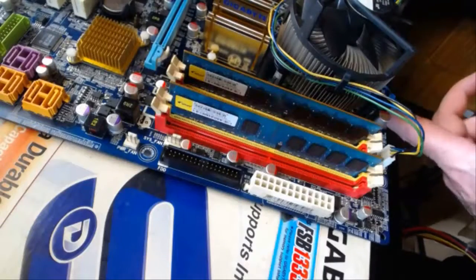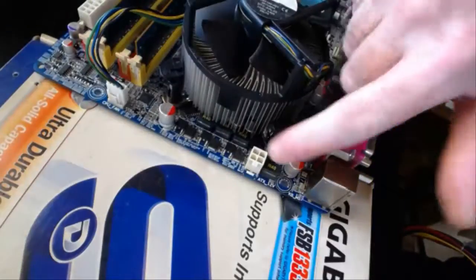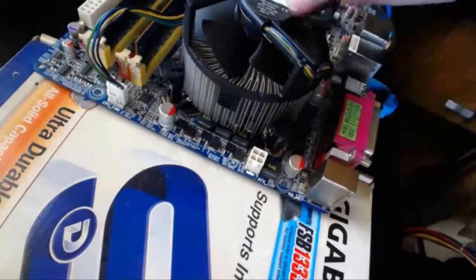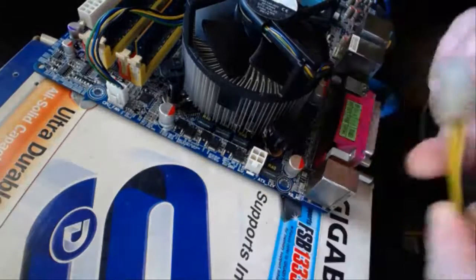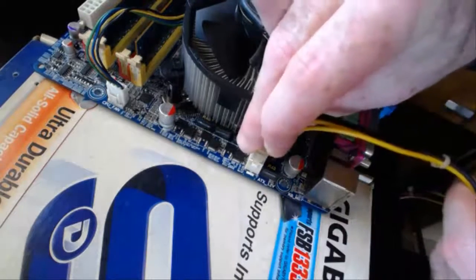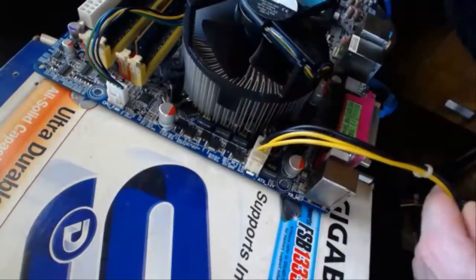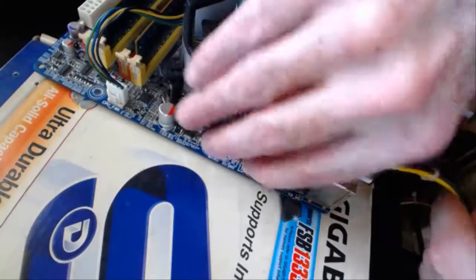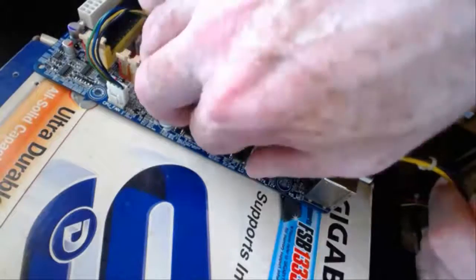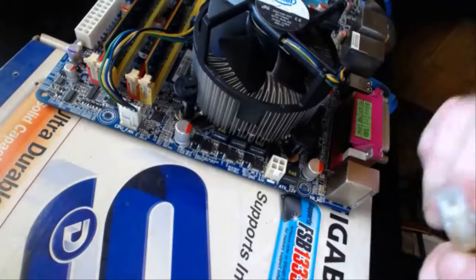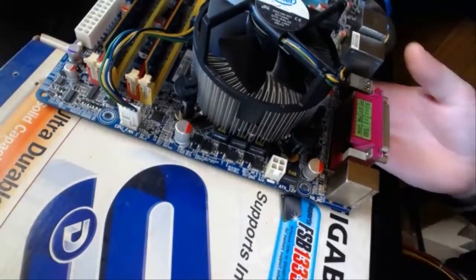And let's see, we'll show you the 4-pin connector as well while we're at this. So this is the power that goes to your CPU, okay, and this is the 4-pin connector that connects to it. Just drop that down into that there, same way as the last one. Just push it down into it, and that's it, connected. And then to remove it, you just push on this little guy here, and it pops up out of it. Now they are tight, so again be careful.